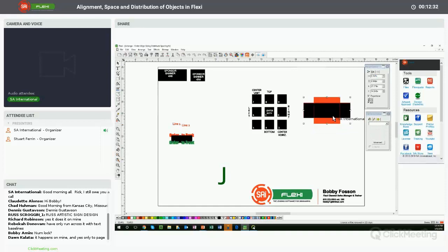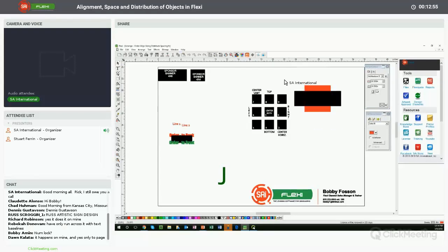And again, this may be my keyboard that I'm having trouble with, because going back and forth to these different ones, it seems to be working in some cases and some not. But again, it should, by using the Control key, select these two objects and basically go to the top, the bottom, the right, the left. Again, both centers are 5, and it should pop them in correctly that way. So that's really the gist of aligning objects. It doesn't have to be just rectangles. It can be any object, really, for that matter.